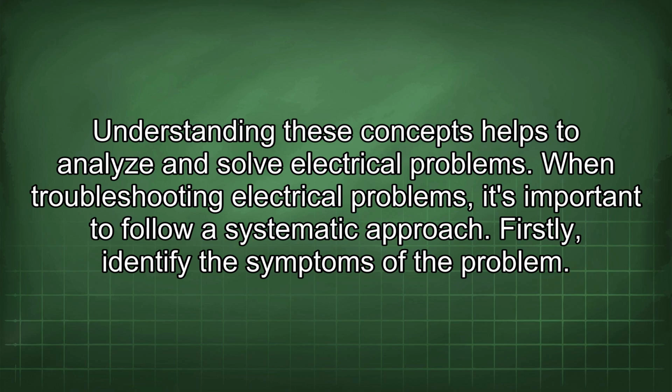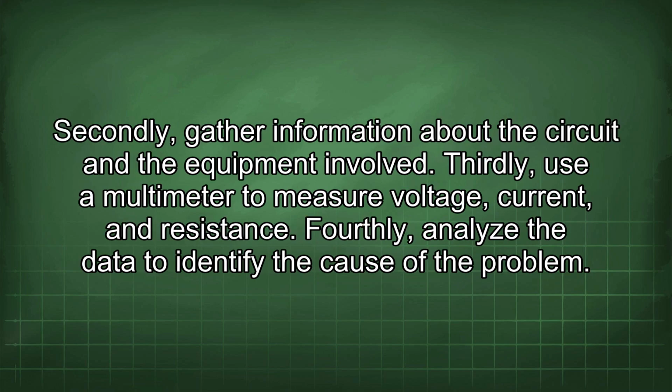When troubleshooting electrical problems, it's important to follow a systematic approach. Firstly, identify the symptoms of the problem. Secondly, gather information about the circuit and the equipment involved. Thirdly, use a multimeter to measure voltage, current, and resistance.